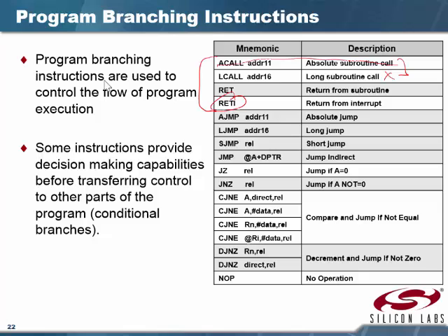If you use the long call, it will always work. Or you modify your code someplace else, those two subroutines get spread out, that subroutine gets moved down a little farther in memory when you compile it, and now all of a sudden it doesn't work anymore. So it's a little risky using the A call.